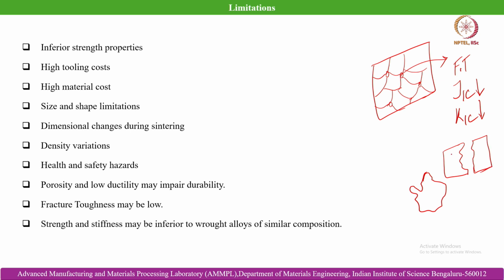If I consider that the preferred powder metallurgy route is injection molding, then there are the male and female halves of the die cavity. That cavity needs to be machined, and that can result in a much higher cost, which you can otherwise avoid in casting or forming routes, because you can leave extra material for machining.